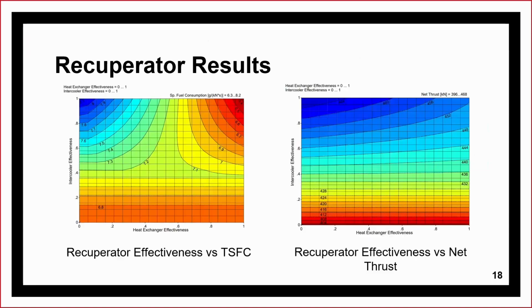The next improvement to the geared turbofan we investigated focused on cycle improvements through the use of an intercooler and heat exchanger. Unfortunately, GasTurb does not have a model for geared turbofan with an integrated intercooler and heat exchanger. We instead modeled a 3-spool turbofan to match the geared version's thrust and thrust-specific fuel consumption as close as possible. One thing to briefly mention here is that GasTurb does not allow parametric studies of the recuperator effectiveness to show values of thrust, thrust-specific fuel consumption, etc. For this reason, we perform parametric studies on the combination of an intercooler and recuperator at the same time.